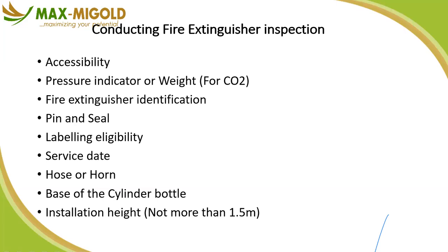That's the point. The extinguisher also needs to have pin and seal at all times. If the seal is not there, then it's assumed that the extinguisher has been used. So you need to also inspect and confirm that it has not been used. The pin is sacrosanct, charge of the extinguisher.